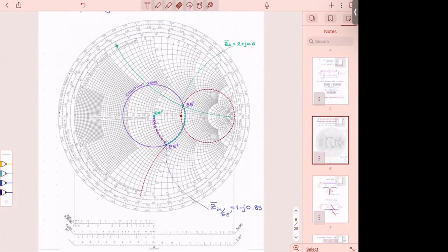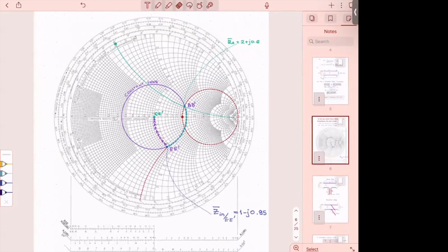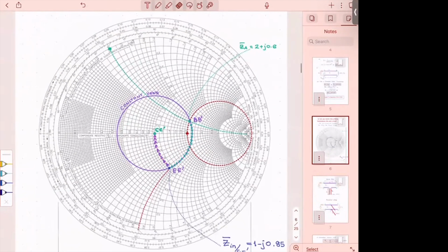We said the first thing when we want to design, we did the impedance matching. We did the hybrid design that involved a transmission line and a lumped element by using a capacitor and a quarter wavelength transformer. All right, it is in the notes that we did last time.